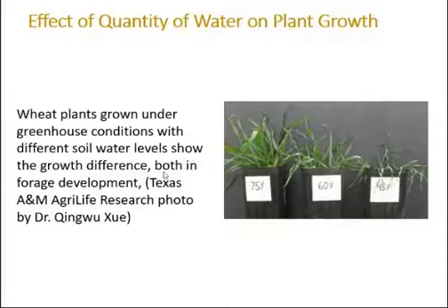So what you have to do is keep the water in the stage of the available moisture content. You try to keep it in that range, and you don't allow it to fall beyond that range. You don't allow it to go to saturation, and you don't allow it to go to the permanent wilting point. You maintain it at the available water content.